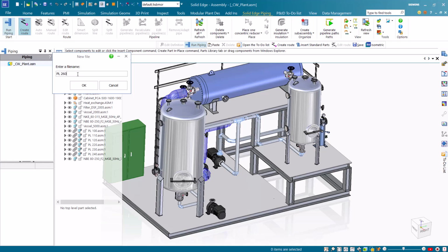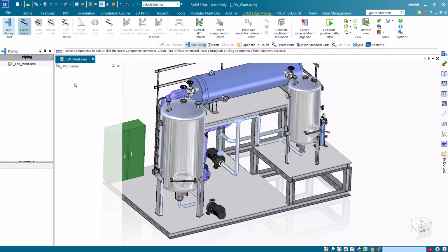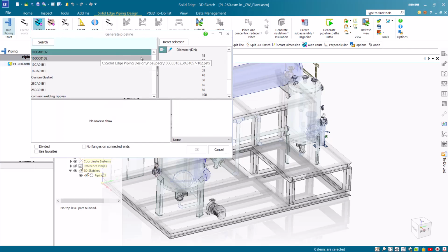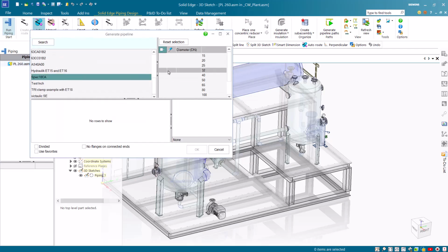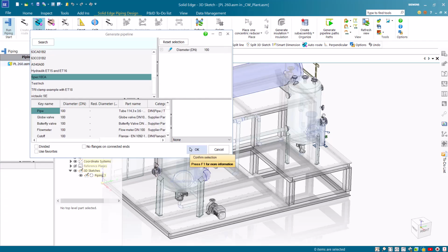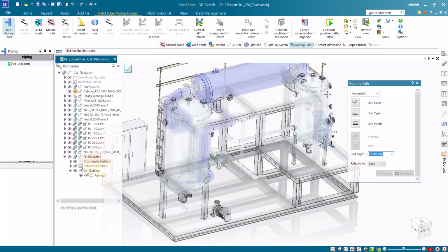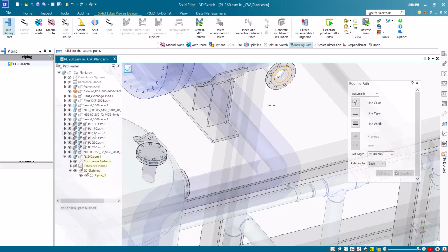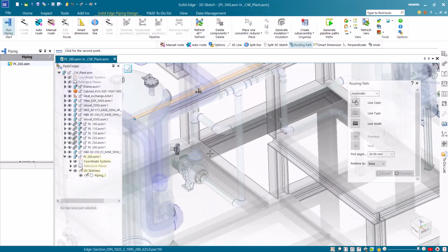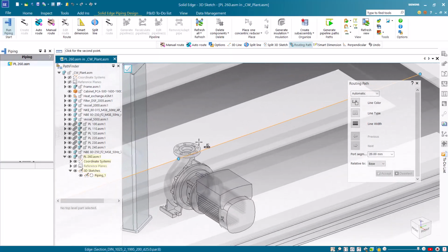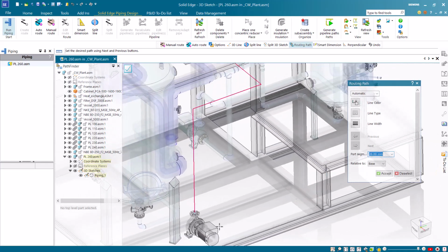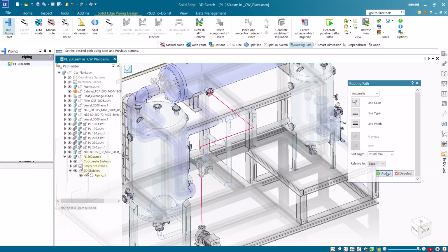For this, we can use 3D sketching tools and select the piping diameter from the pipe specification. However, this pipe diameter can be applied on existing pipe line sketch later, or even pipe diameter can be changed. Here, let's select a 100 diameter pipe from the pipe specification. These sketch lines are associative to end connections and geometry can be constrained as required.